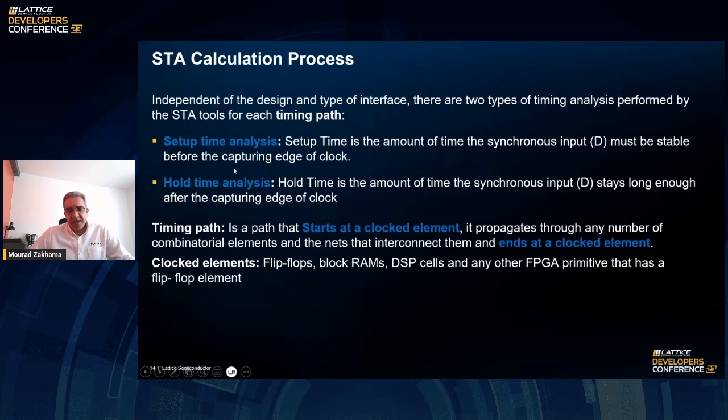Like we've seen in the flip-flop, it's exactly the same thing. We are making sure that there is no setup time violation for all the flip-flops, meaning that the data is stable enough before the clock edge to guarantee the transfer of that data to the next stage by the flip-flop. The hold time is the same way.